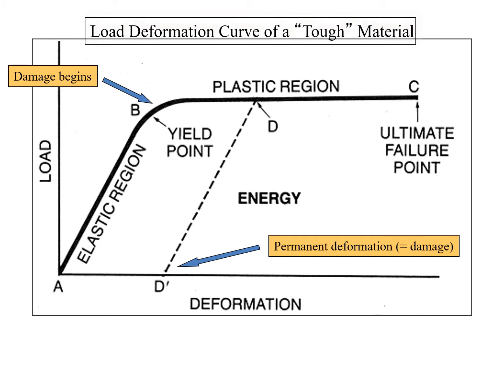The relationship between the load applied to a solid and its deformation can be represented graphically, and that's what's shown here. This is a load deformation curve. The load is on the y-axis and the deformation is on the x-axis. This is actually data from a human femur that is being pulled in tension from both ends of the long axis of the bone. There's an initial region in which you're adding this tension and the bone is deforming a little bit. That's a pretty linear region, and as I mentioned, initially that bone, when the load is released, will move back to its original shape. So that's the elastic region.